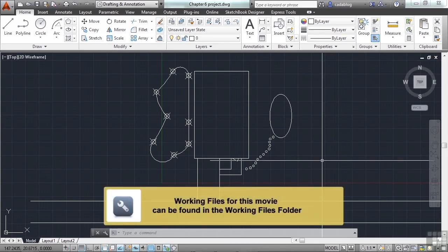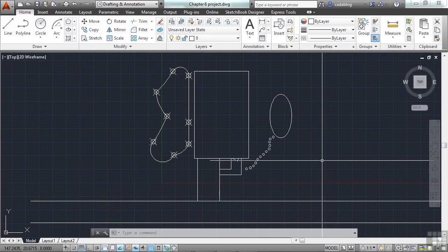As in most projects, you have to make a mess in order to build something. AutoCAD is the same way. In order to create your designs, we will have to make objects in them that ultimately we don't want. A lot of times those objects come in the form of a construction line or some sort of drawing aid. Whatever they are, they need to go away. So to do this, we use the erase command.